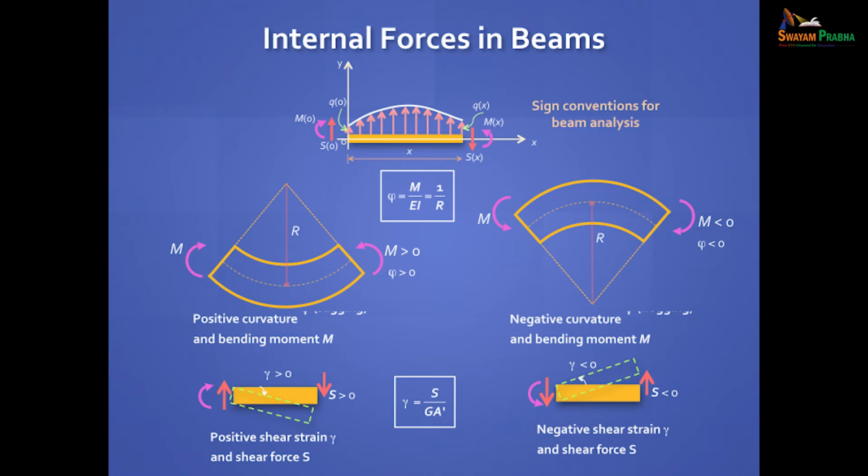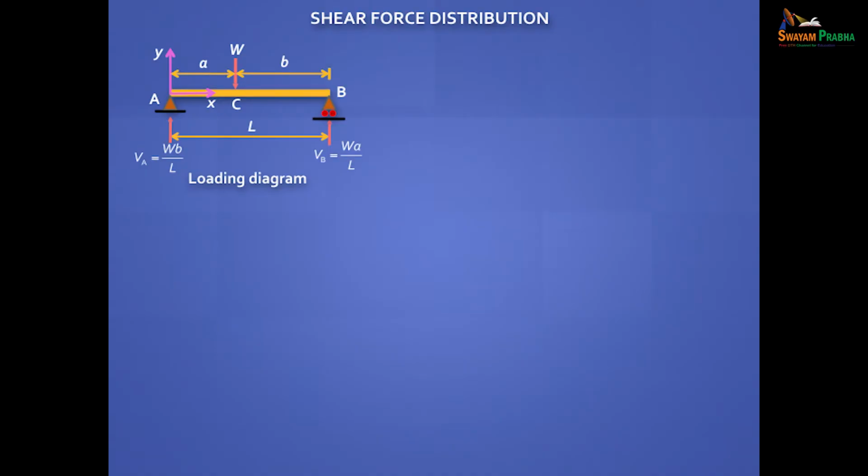Now let's just go through the basics which everybody learns. Standard drawing, you're given a simply supported beam with a concentrated load. We've already learned how to find the reaction. We know many methods to find the reaction. Very simple logic: will this reaction be more than this or less than this if A is less than B? Left reaction will be more, and very simple.